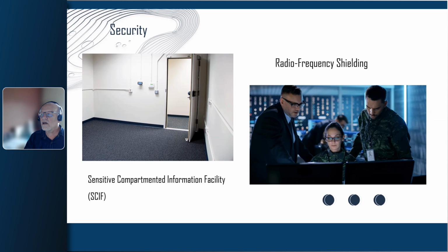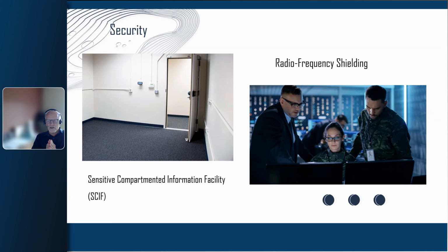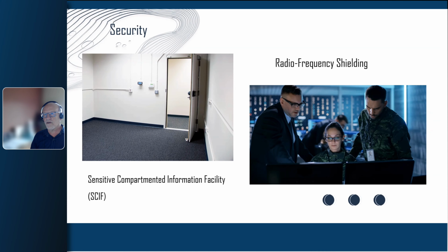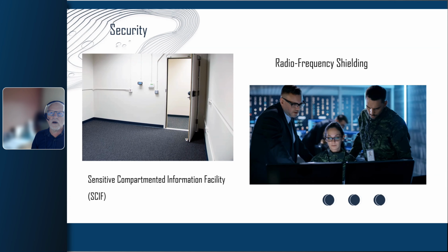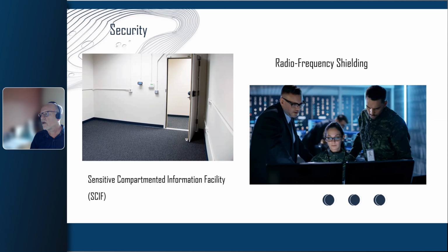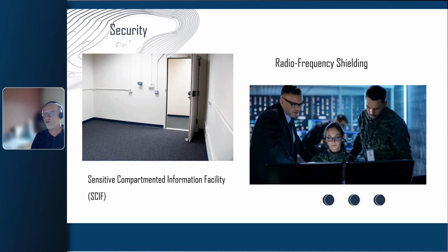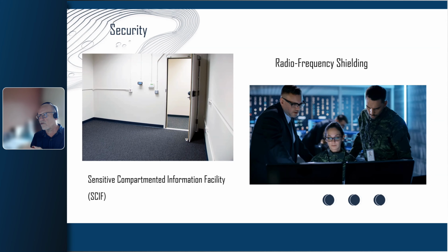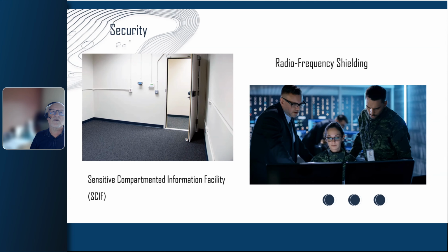So radio frequency shielding is measured in decibels and in frequencies, but the measurement is for radio waves, not sound waves. They are very different. That being said, it's become commonplace on certain types of projects, particularly if there's a military or a governmental requirement for radio frequency to be a factor on an acoustic door. So you've got an acoustic door that has an STC, let's say, of 50, and you've got a radio frequency requirement at 60 decibels of radio frequency.